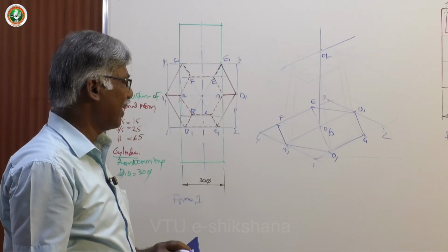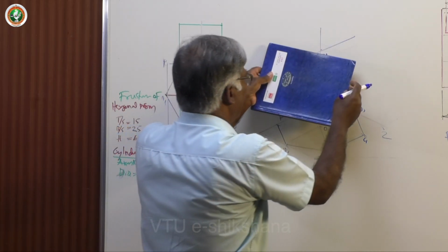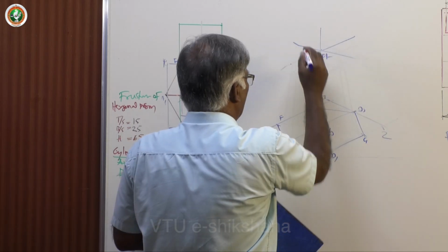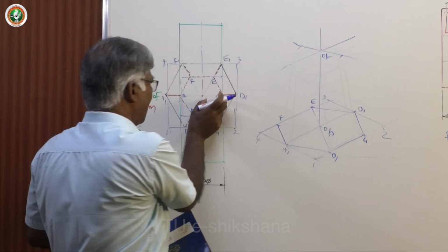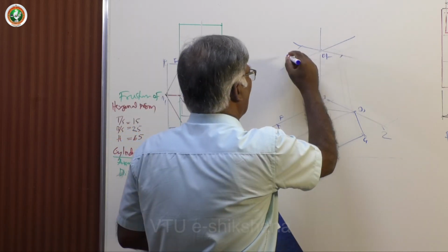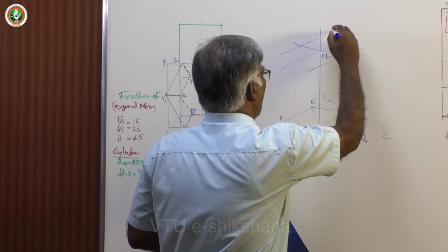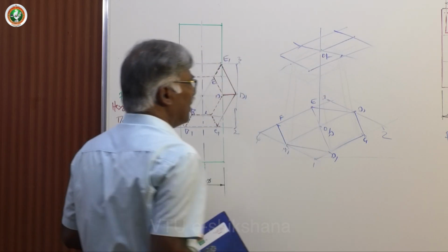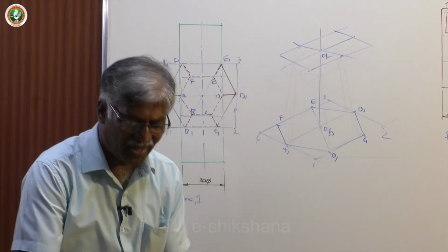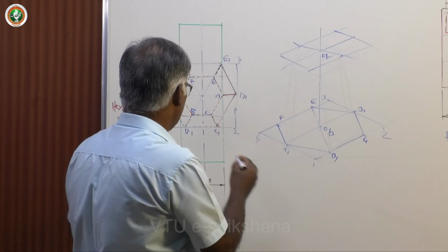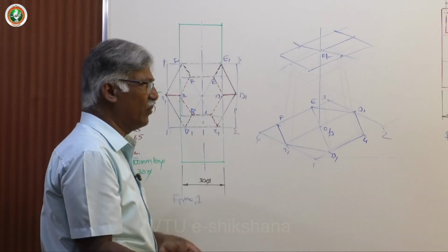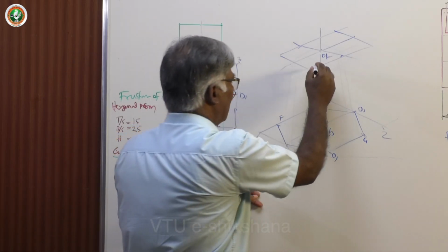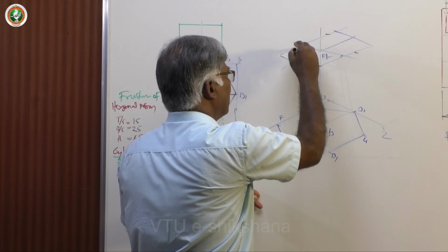Very easy to learn. Then draw again 30-degree line. Should get on this line, mark the distances, whatever is available here, and draw parallelogram. So this is for top face. Identify the respective points here again. Enclose it in a box and do it. In case of computer, you scale it and do it. You need not do all this. Manually, you have to do this.